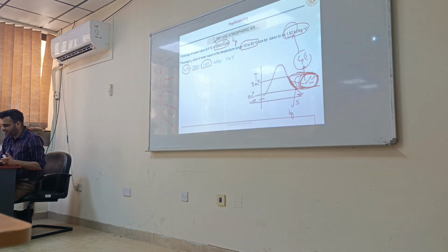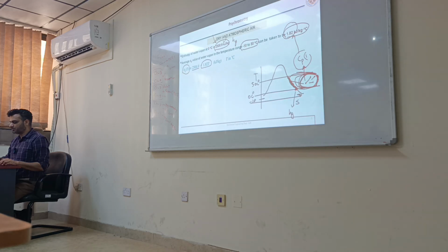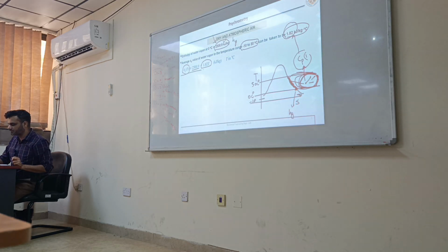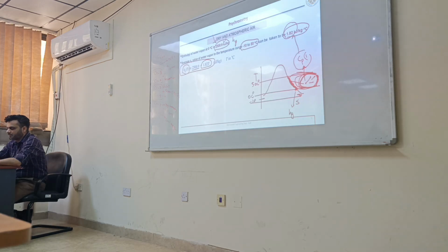If you do not want to use that assumption, use the table. If you do not want to use the table, we can use that assumption to find enthalpy at any temperature T. That represents Hg plus Cp times T. Actually it is delta T, but we are showing it with reference to 0.